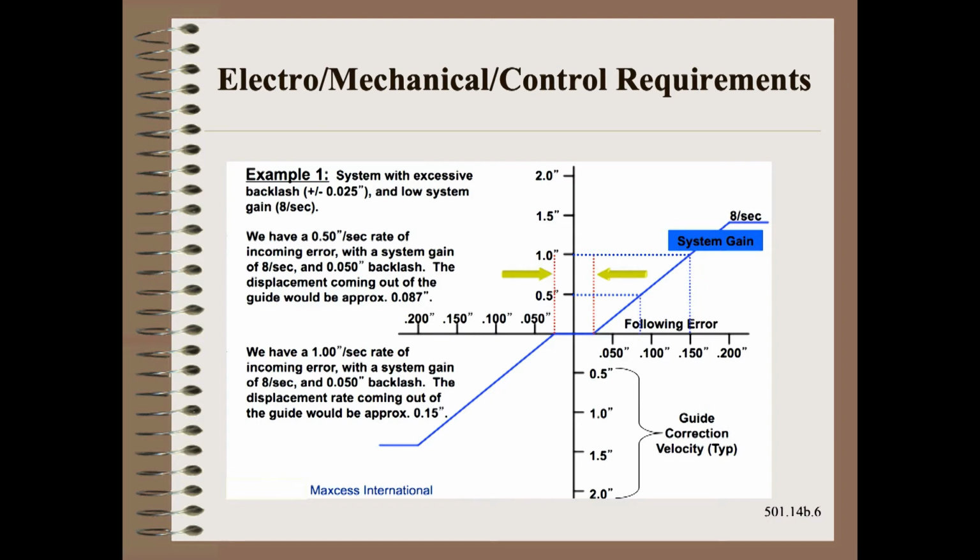In addition to stringent path routing requirements specific for each guide type, there are also electrical, mechanical, and control response requirements with regard to backlash, deadband, and maximum stable gain tuning of the PID loops.